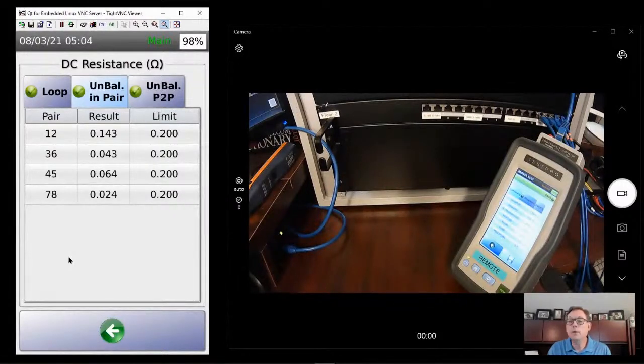And if you have an unbalance, what can happen is because of that skew, if you will, in the power delivery, you're going to have issues with your PoE. First off, your delivered power is going to be problematic. It may impact the data that's traveling on your cable, so you may have issues with your network. Additionally, you can also have issues with cable heating up.